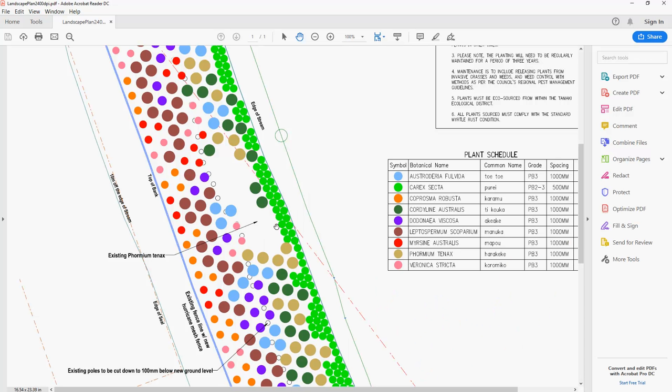Contrast that result with this result where we had transparency for that polyline area there, and we don't get it to show in the final print. So avoid using transparency if you want high resolution PDF output from gCADPlus.